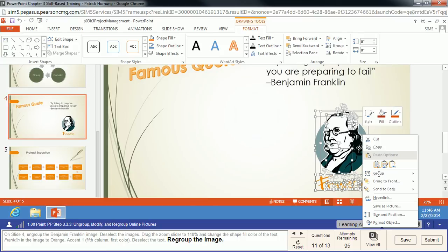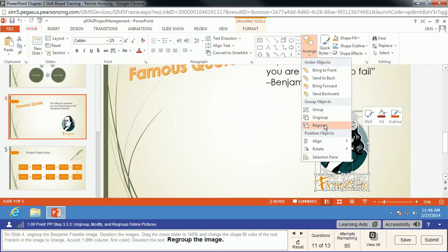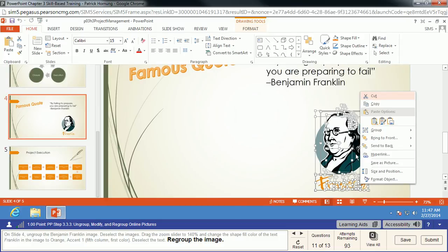But there's one method, and only one method, that I've found that has been able to get this step to work. And that is a Shift F10, the letter G. Oops, let me try that again. Shift F10. I'm going to reselect him here. Shift F10 should bring up your right-click menu, and then if you type the letter G, that right-click menu will actually let that work. But for whatever reason, when you do the right-click with the mouse, it doesn't activate that subset of stuff. And then Enter. So we're going to leave it on Group and just hit Enter, and it does click on through.